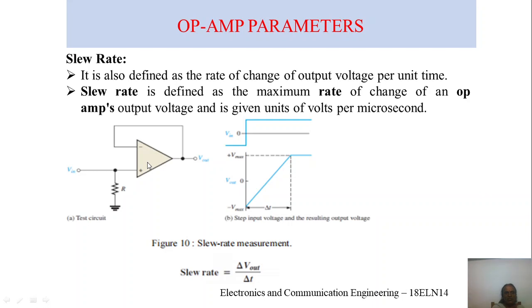The high frequency components of the voltage steps are contained in the rising edge, and the upper critical frequency of an amplifier limits its response to a step input. So the slope increases as the upper critical frequency decreases.